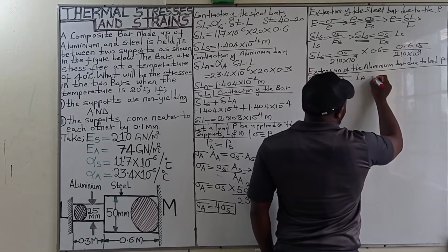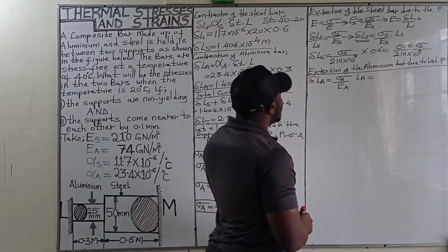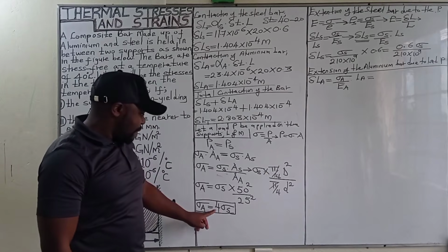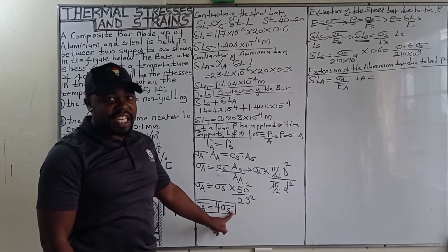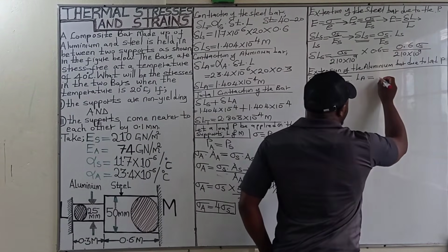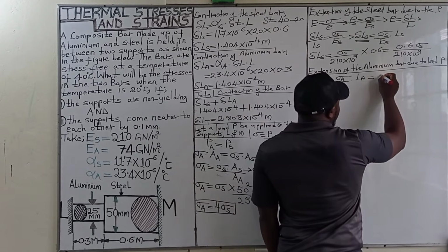So this will be equal to the stress in aluminium, we had it as 4 times the stress in steel. So we are going to substitute that one here.